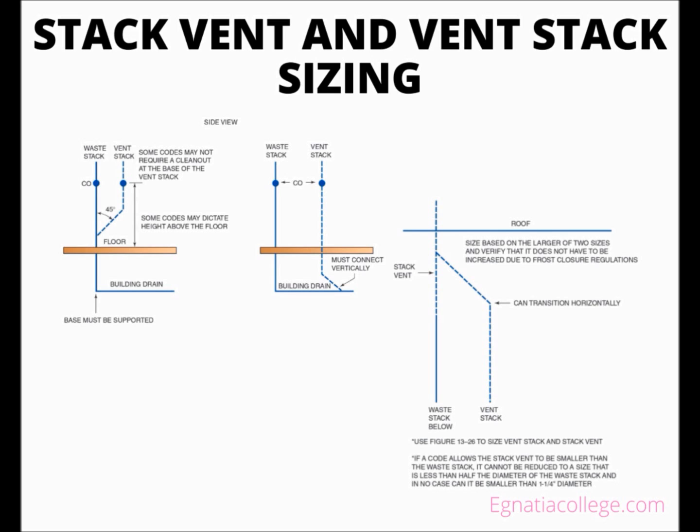This results in different sizing approaches for a vent stack and a stack vent concerning the DFUs connected to each segment. If vents serving a horizontal drain that is connected to a building drain are routed to areas other than the vent stack, the DFUs of that drain do not have to be considered in the total vent stack DFU value.